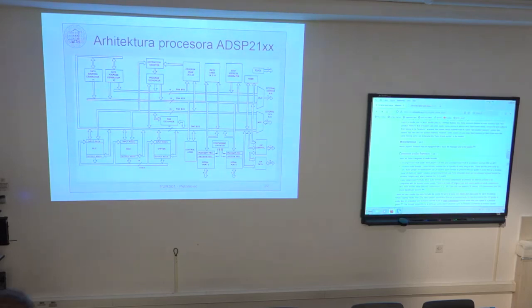The actual DSP that is used in the laboratory exercises in your simulation has an instruction word that is either 32 bits wide or 16 bits wide. But these instructions are packed in a packet that can be executed in parallel. For example, you might have a 32-bit ALU instruction combined with 2 load or store instructions, and these load or store instructions are 16-bit encoded.